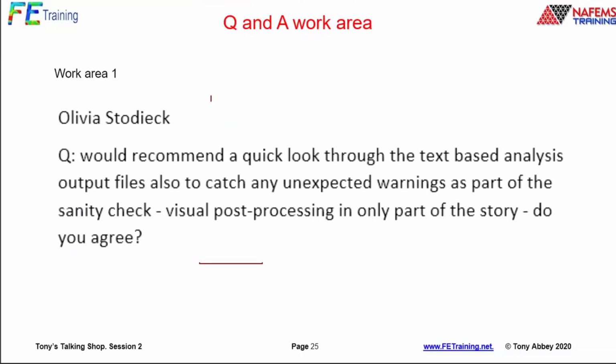So Olivia says, would recommend a quick look through the text-based analysis output files, also to catch any unexpected warnings as part of the sanity check. Visual post-processing is only part of the story. Do you agree? Yes, I absolutely do, Olivia. Again, I haven't really focused on this, but for example, where do you find the peak deflections and the peak stresses? I actually normally look in that summary output if it includes them.